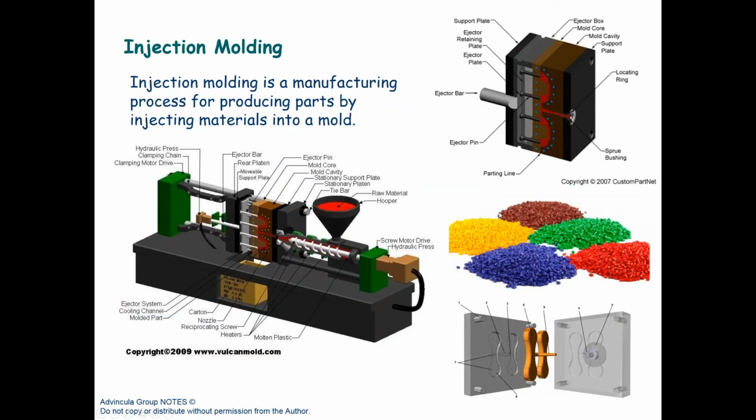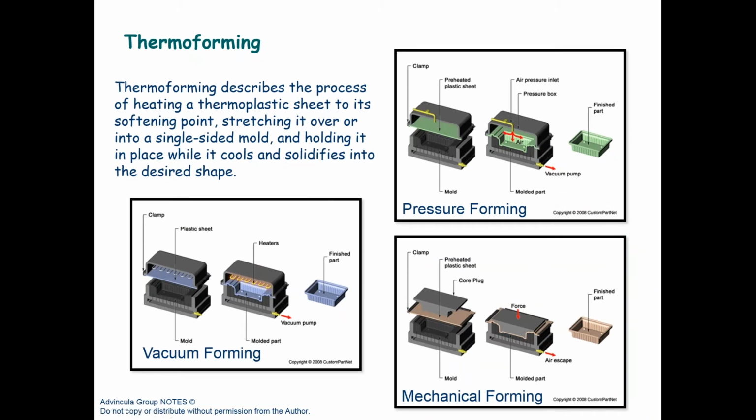Here's a picture of injection molding, and you can see in molding fabrication, you have a mold which can be based on aluminum, and the melt resin is added to that mold, and you produce your object. Yet another traditional method of manufacturing is based on thermoforming, where the application of pressure, vacuum, or mechanical pressing of a sheet produces a finished part. So one would say that these traditional methods are not under threat